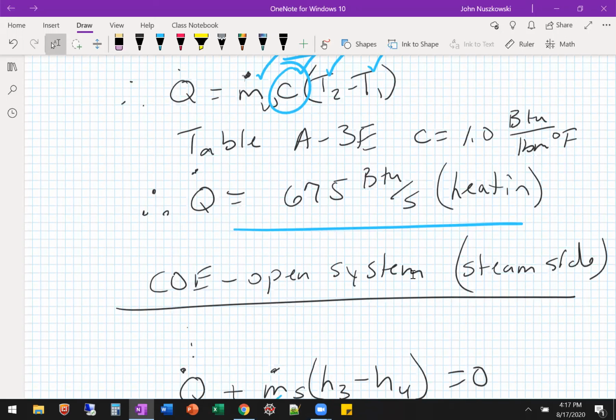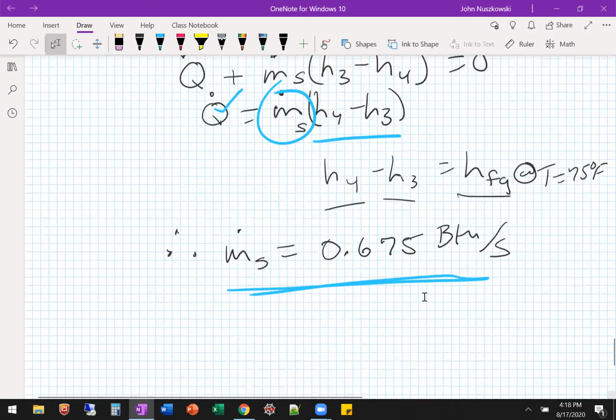So whenever it's water or steam, you always want to first start with tables. Tables are always right. Ideal gas and incompressible substance are sometimes right. So you have to know when you can simplify to something like that. Steam is a very vague term that people use, and it could be in the superheated region, it could be inside the dome. And when you're inside the dome, there's tons of latent energy. Other questions? That was a good question.